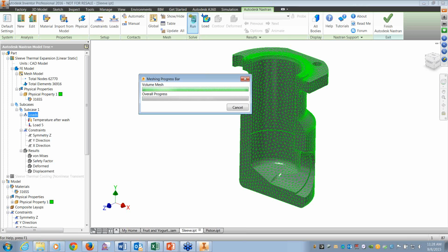relationship between the two. While I'm trying to kill a little bit of time while the analysis is actually running, I'll point out also that with the Inventor Professional, we've been limited to linear elastic, which means that pushing on something twice as hard gives you twice the deflection, twice the stresses. That's good for very small displacements. It's where that assumption works best. But what we run into too often in the real world is you can't get away with just that basic assumption.